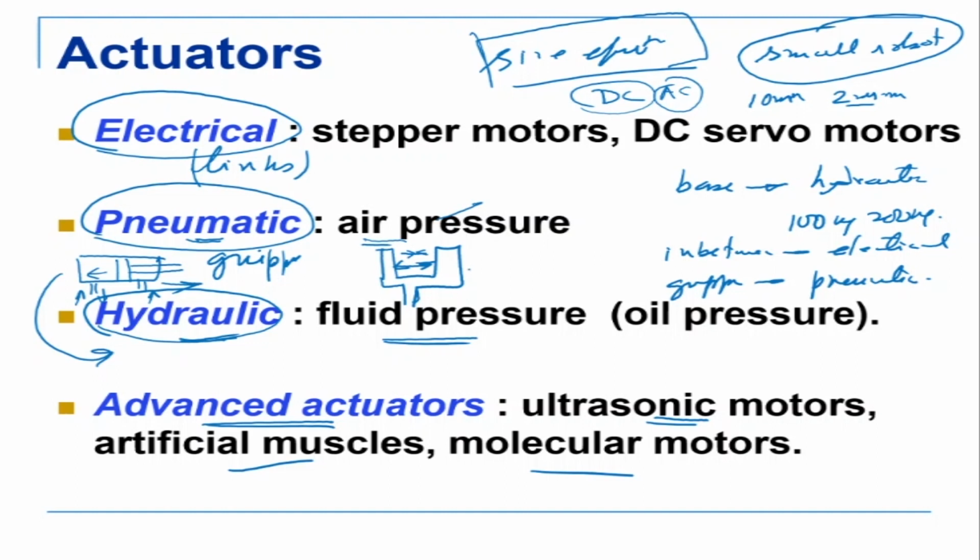So if you press it in this direction, for example, we have a robot like this, and it is holding the end effector. There is a part and it hits something here. What will happen? The gripper can immediately open, or the shock of getting hit can be transmitted onto the pneumatic actuator. It can go backwards, or it is back drivable, whereas other actuators are not back drivable. Okay, and because of this, grippers in robots are very often pneumatic because they just open and close, whereas the in-between joints are electrical.